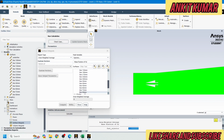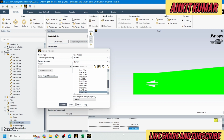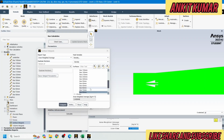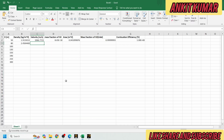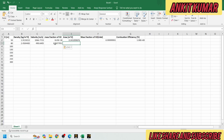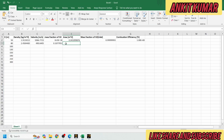So I will select the line 80 mm, and now quickly I will calculate all the values. Density value at line 80 mm: select it, press compute, Control C, then write the value here. Now velocity: press compute, 490, Control C, paste it. Again, mass fraction of the hydrogen, species mass fraction of hydrogen is already selected. Press compute, copy this value, go to Excel, paste this value. Next, area is required at 80 mm. From area weighted average, select area, press compute. This will give the area value. Control C, paste it.